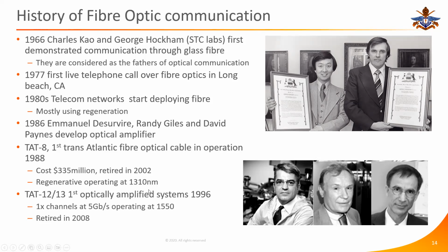Now, this was a regenerative system. That means under the sea, there are amplifiers that convert from optical to electrical. Electrical amplifiers amplify the signal and convert it back to optical. So TAT8 was such a system.